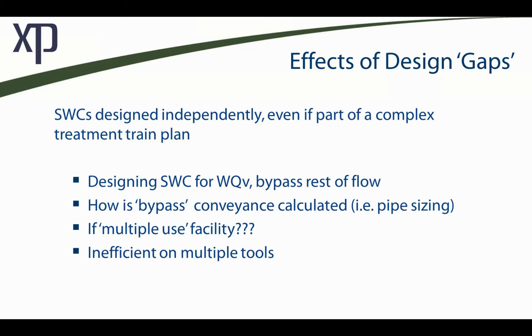Okay, so we can infiltrate the water quality volume with this dry swale. But for higher events, that swale is going to act as an attenuation facility. Okay, and we can store volume in the swale so that we can release it at an appropriate rate and release an appropriate volume. That is something we really can't do with spreadsheets.